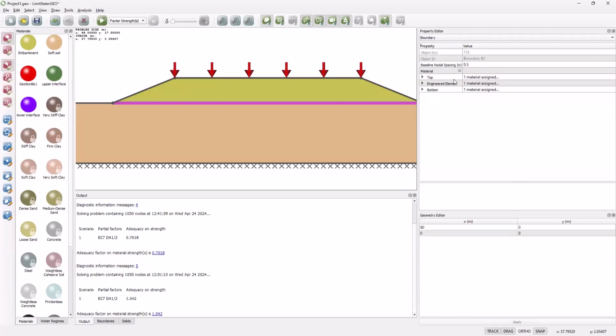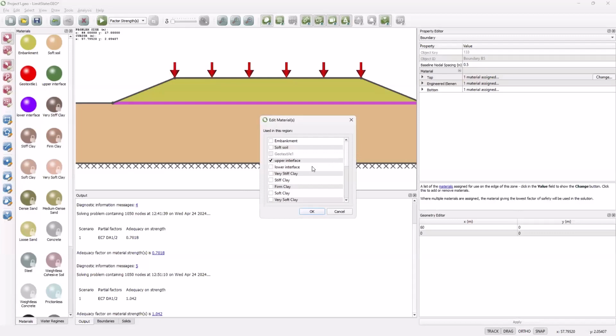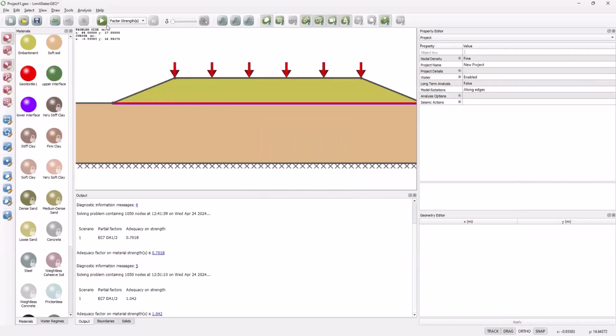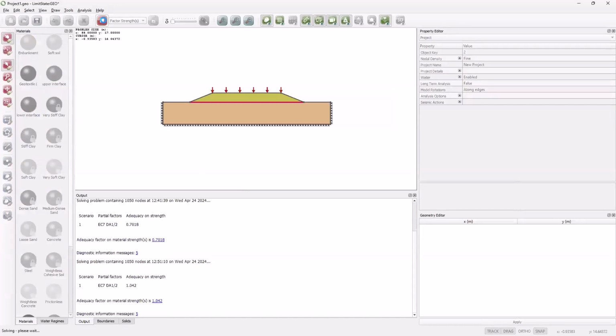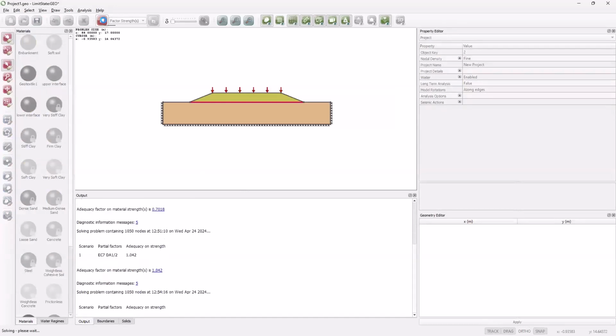If I were to replace this top material, if the embankment was simply sliding on our original soft soil rather than on the geotextile, so if it's sliding on the geotextile, we're getting that sort of frictional interface, an extra strength. But if the geotextile wasn't there, but the soft soil was remaining sort of monolithic, then we would just get sliding on that surface, and we'll see that in a moment. Hopefully we'll just get a sort of corner failure of the embankment as we iterate to the final solution here.